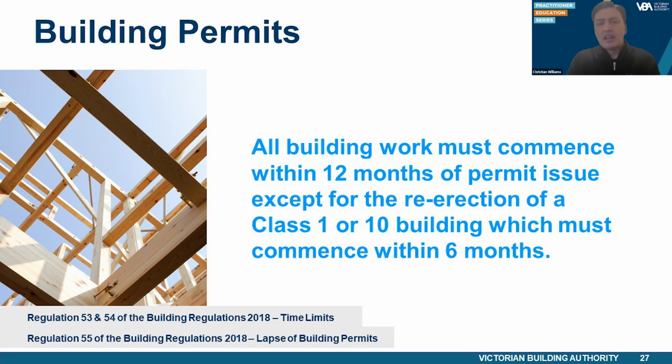Building work must not be carried out unless a building permit is issued and enforced under Section 16 of the Act, unless an exemption otherwise applies. A building permit remains in force for a prescribed period in which the building work must commence and must be completed. This is to ensure that the building work does not remain unfinished or is potentially unsafe or unsightly for a prolonged period. The RBS must ensure that the appropriate dates are specified on the building permit.